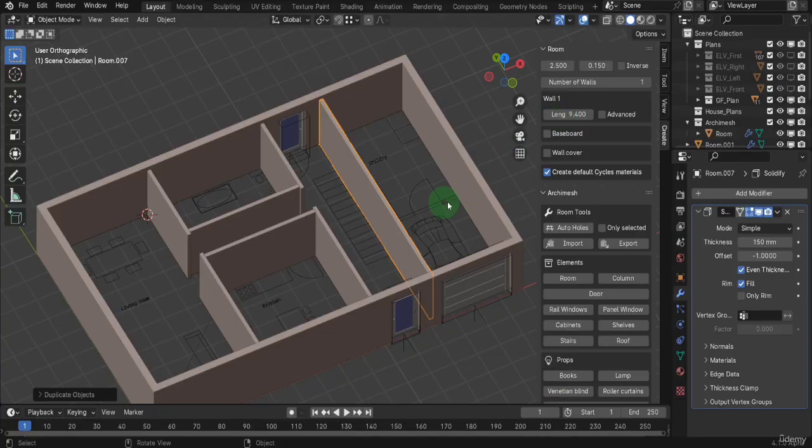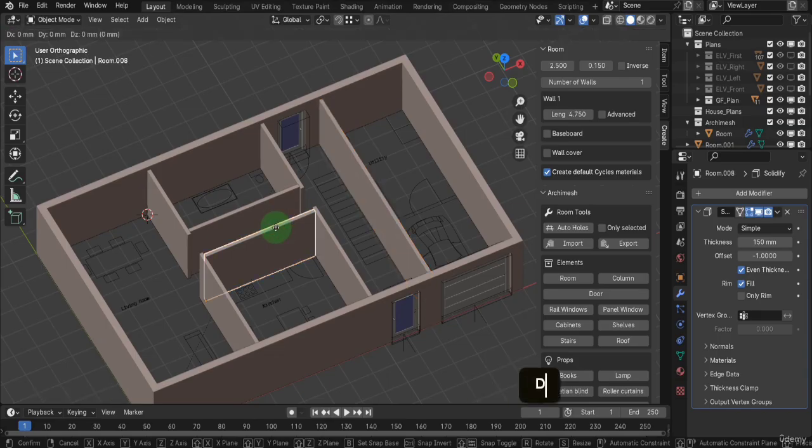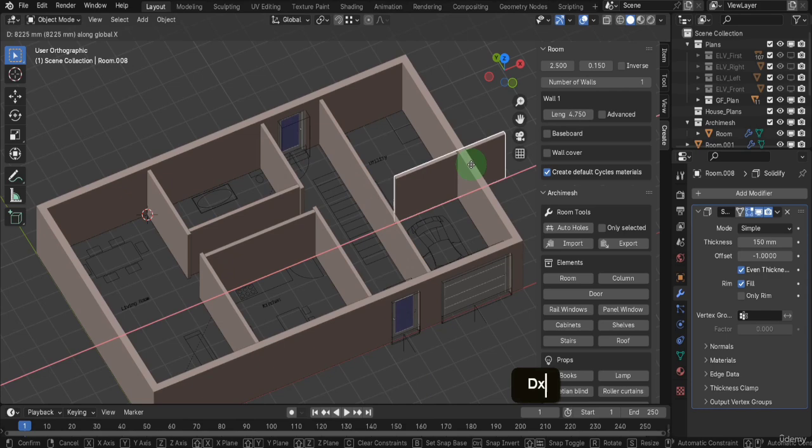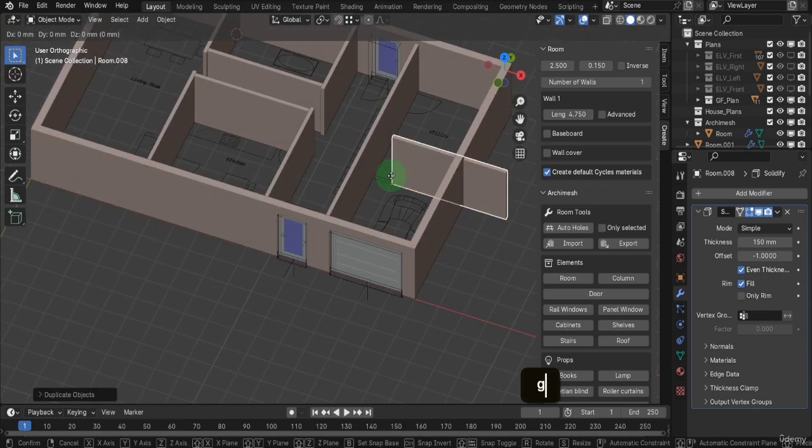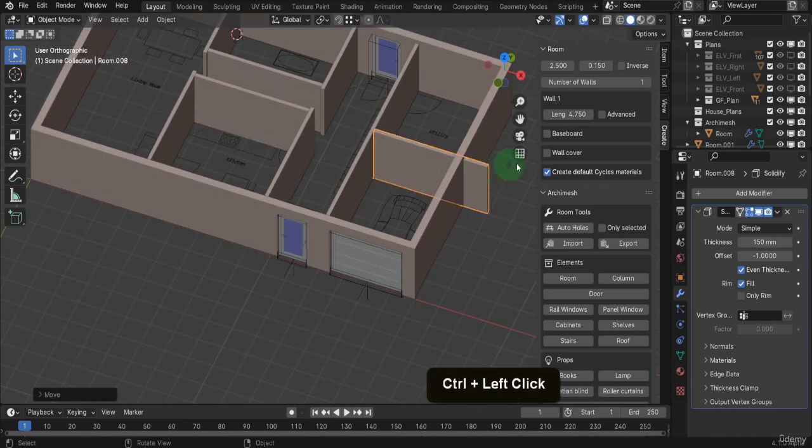The final wall is into the garage here. Select one of the walls running the same direction. Press Shift plus D, X and drag down past. Then G and snap to the endpoint. That way we can increase this in length and fit across the room. 3.45 works here.